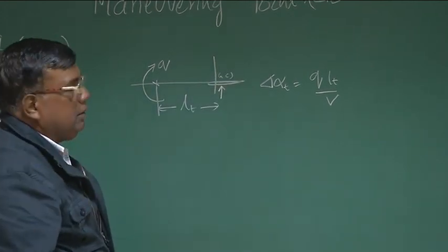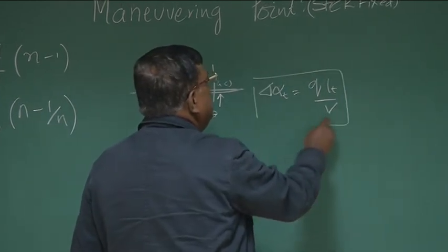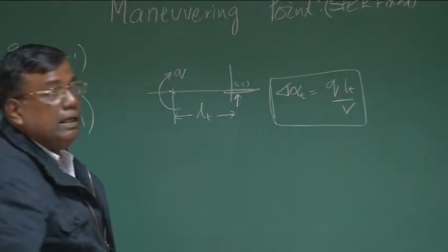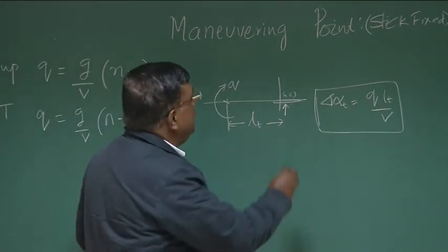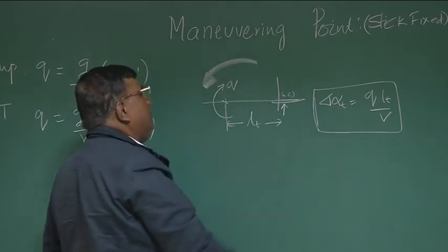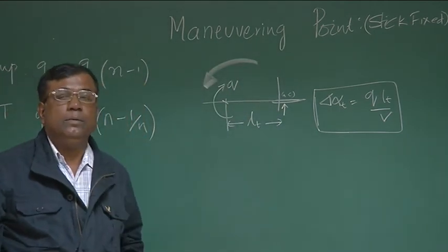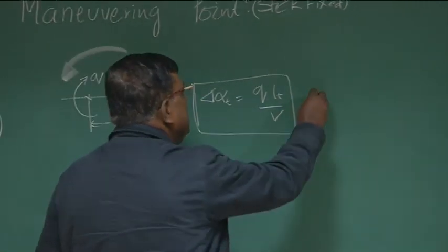And then we asked a question, how much delta E I need to give in addition to whatever delta E is given for cruise, so that this additional angle delta alpha t, which will generate an additional pitch down moment, doesn't happen. So I have to neutralize that. To neutralize that, how much delta E is required?